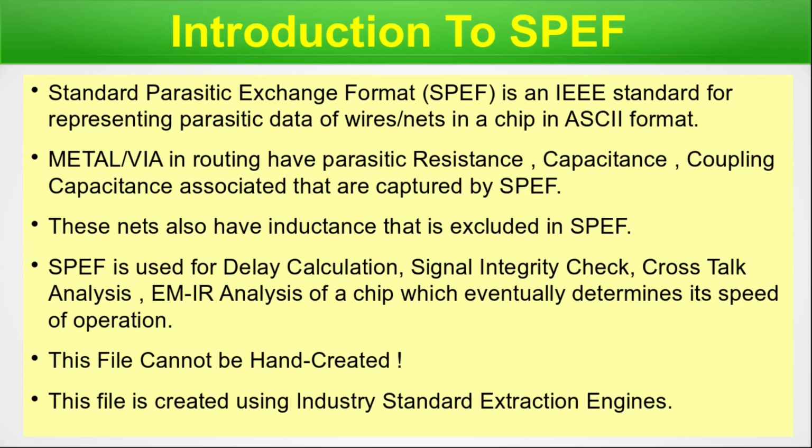So let's move on. Post layout parasitic visualization. In this slide, you are going to visualize the difference that the SPEF file makes on top of the actual design. In this slide, we will overlay the content of a SPEF file over our design. This slide is for educational explanation purpose. Hence, the circuit diagrams are kept in an oversimplified format so that you can grasp the meaning quickly and easily.